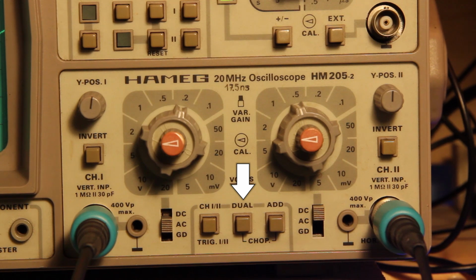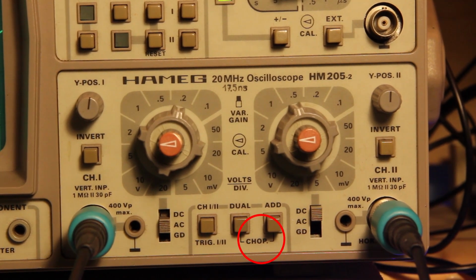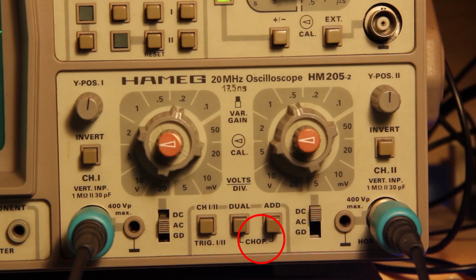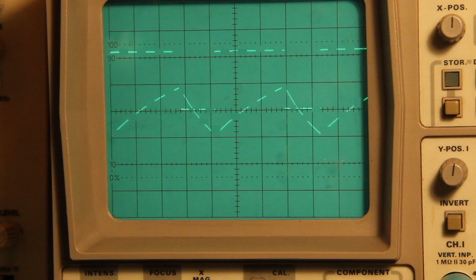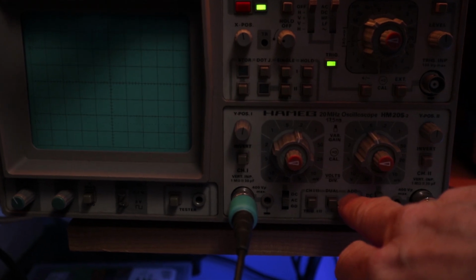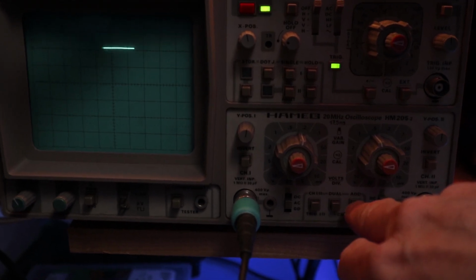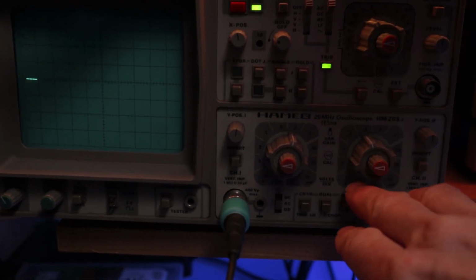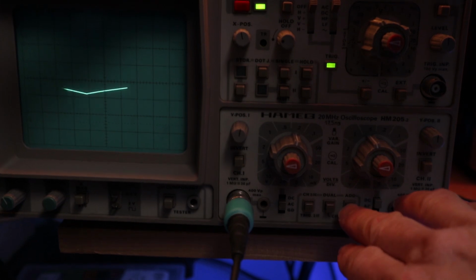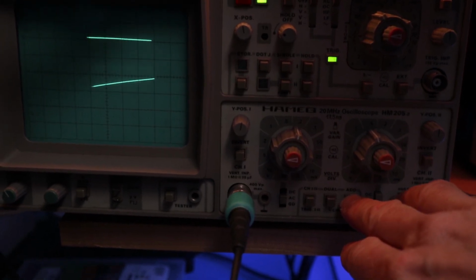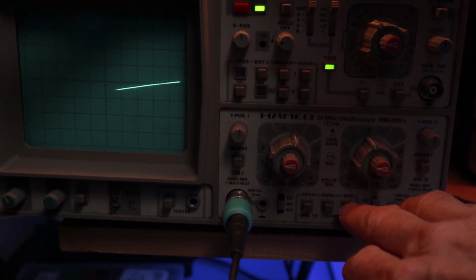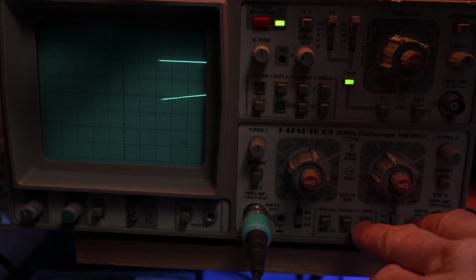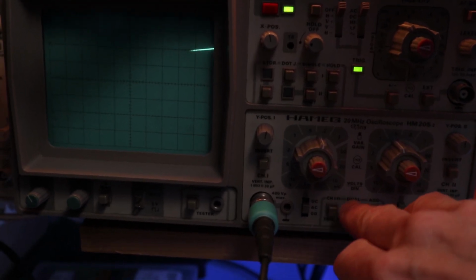When using dual or more traces on analog oscilloscopes, we have a special control that inserts a chopper that chops the signals into slices that are alternately displayed on screen. This is useful when looking at low frequencies or with long time base. Without this function, the instrument alternates the traces at each sweep, and we choose this last option when we look at high frequencies or with short time bases.